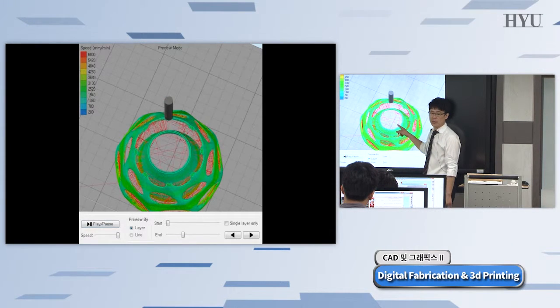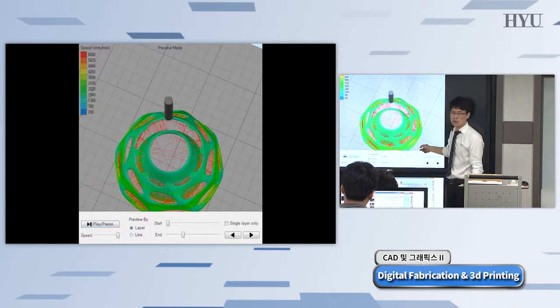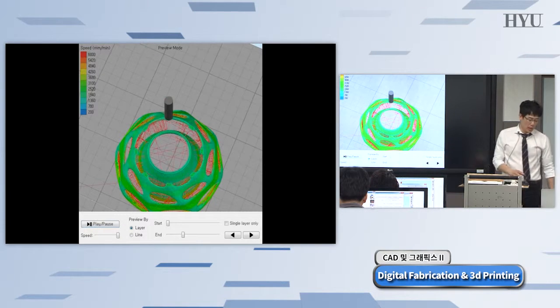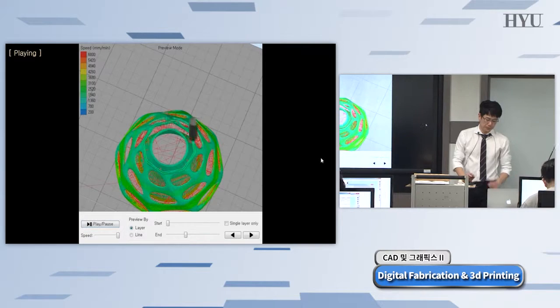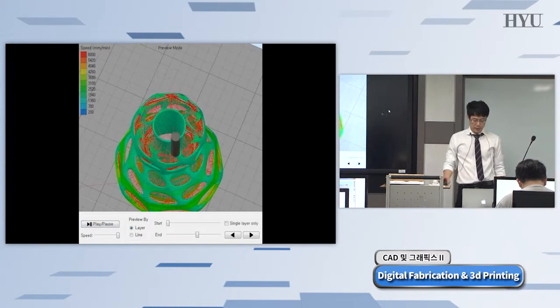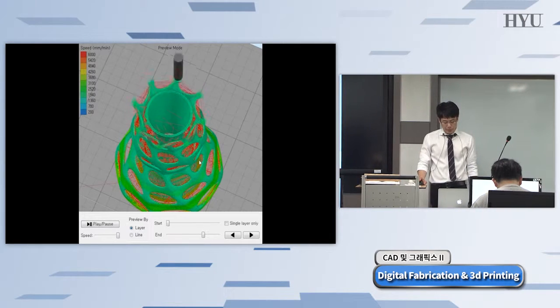The 3D printer automatically creates an inside fill using a honeycomb structure or zigzag structure and so on. No need to fill entirely with material, because that would be too heavy and take too long. So it is auto-generated, or you can modify the structure. At the end, your structure is going to be printed out this way.